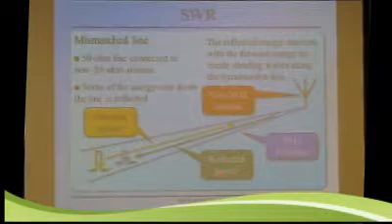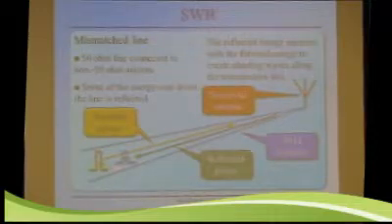But what you're doing is you're looking at the ratio of the high voltage and low voltage points. When you have these standing waves created, you have points of high voltage along the feed line and points of low voltage along the feed line. The standing wave ratio, SWR, is the ratio between the highest voltage point and the lowest voltage point. So if the highest voltage point was 30 volts and the lowest voltage point was 10 volts, then it would be a 3-to-1 standing wave ratio. Now why is that important to us?